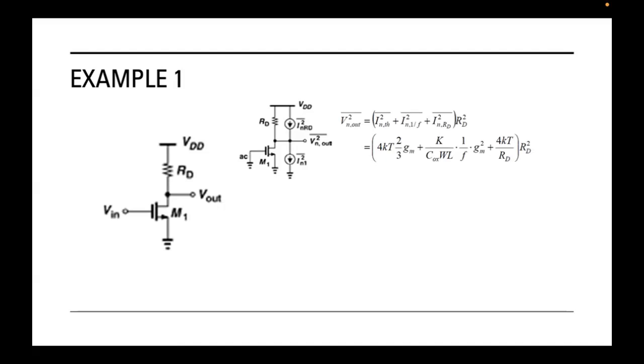Any output recognized at the output terminal when the input is 0 is definitely due to noise. So that's why usually when we do noise analysis, we ground our inputs. Now, when we ground our input, I use that second way. So I am representing the noise as the current flowing into the drain.